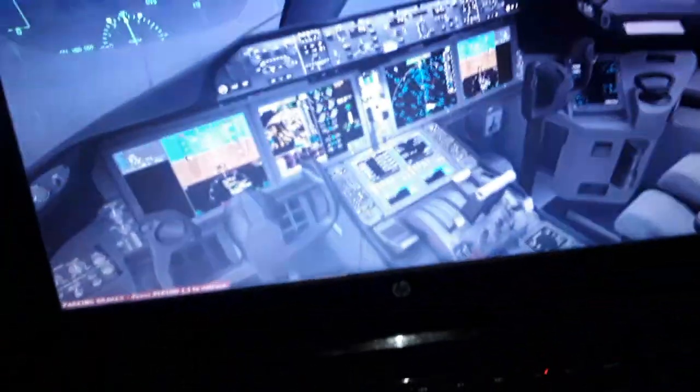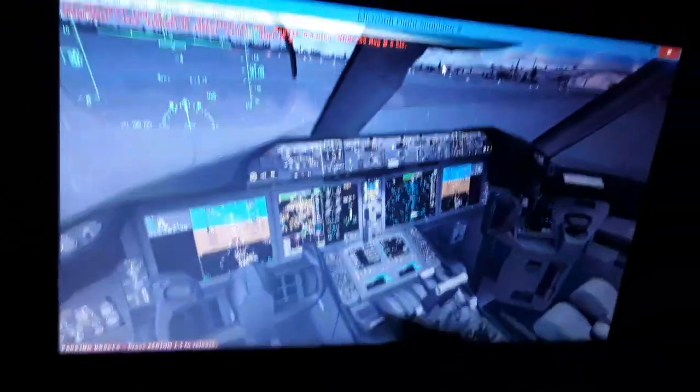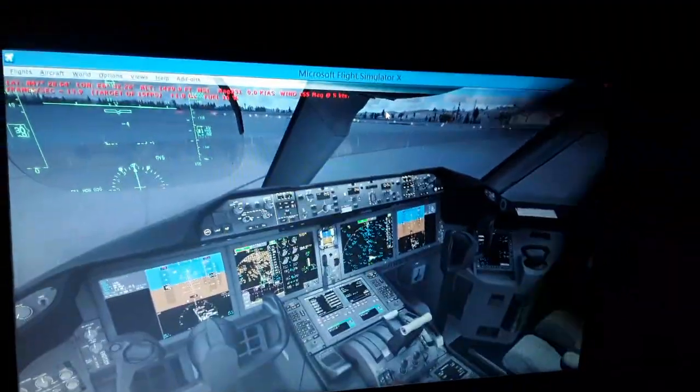We have also the localizer crossbars, the flight director crossbars for manual guidance of the aircraft, and the autopilot crossbars for automatic guidance of the aircraft. We have also the HSI, the horizontal situation indicator with the standby integrated flight plan display. You can see the flight plan here. We have the magnetic heading. You can track the magnetic north pole and true north pole, the magnetic north pole and geographic north pole, and magnetic variation everywhere around the world.